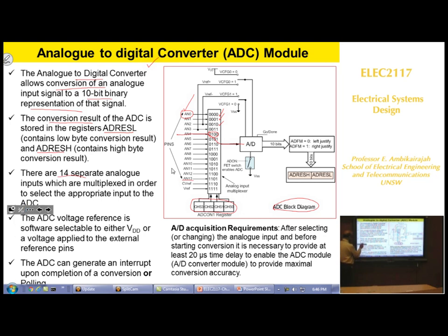The ADC voltage: there are reference voltages. One is the supply voltage VDD, and the other one is the ground voltage. So you can see in this case there are 2 positions where they are connected, and we have a positive reference voltage. You can provide that through that line, and if you set this bit to 1, that will be connected. So that's your positive reference voltage going to the A to D converter. If you want to have the negative voltage, you can also connect them through this and that, and this has to be 1, then it will be connected that way. If it is 0, this will be connected to ground. So you can choose. If you want to measure voltage differences, not just analog voltage into digital, but you've got 2 lines coming in and you want to measure the voltage difference, you will use this particular arrangement. And we have examples to show you.